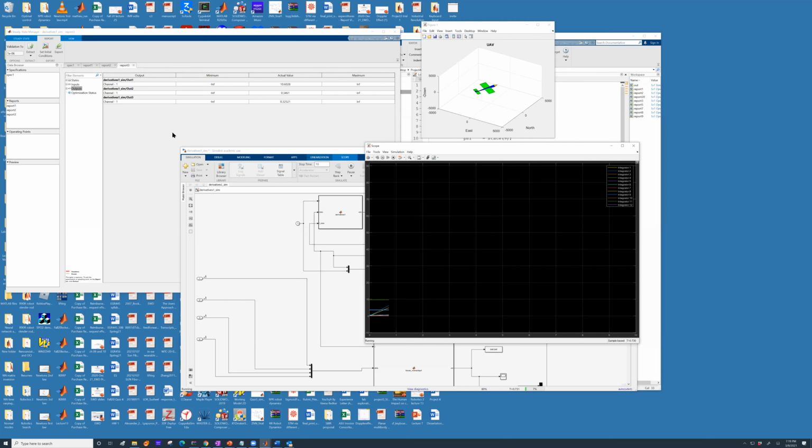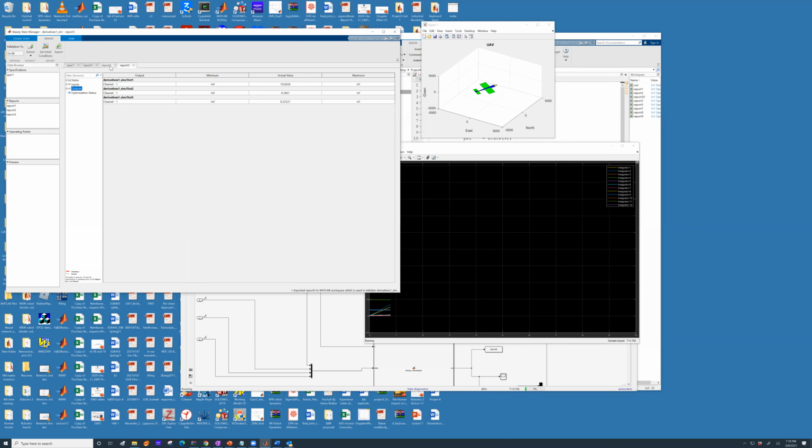And I tell you the reason why the height would change, because if you look at the states, please note the derivative on state 3, even though the state 3 is starting at 0, the derivative on state 3 is non-zero, which means the height is going to increase, and which is quite natural, because as your aircraft is pitching up, you would expect the height to increase. All right, I'm gonna stop here,